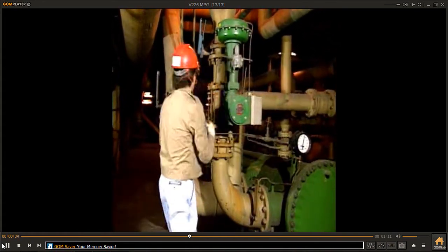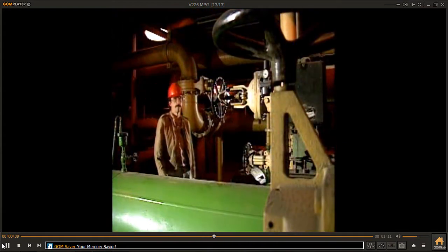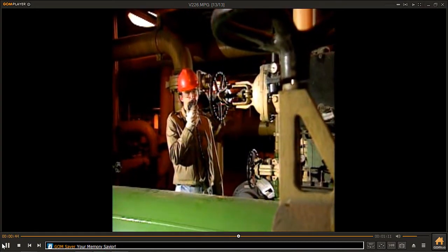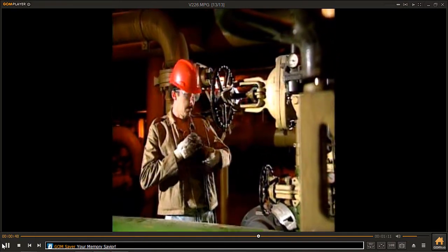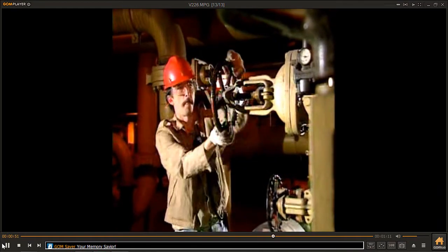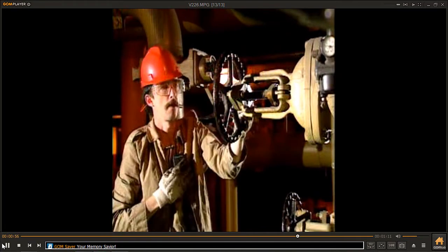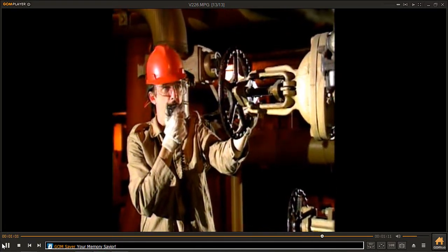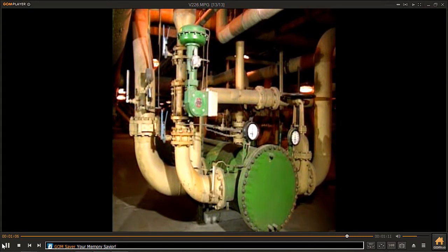Bypass lines can usually be placed in service by isolating the failed actuator's control valve and positioning the bypass valve to restore flow. When either a manual operator on an actuator or a bypass line around an actuator is used, it will probably be necessary to maintain communications with the control room to ensure that the proper flow rates are maintained in the process. Since there are so many different possible configurations that actuators and control valves can be arranged in, you should check your company's procedures before operating any actuator manually or on the bypass.